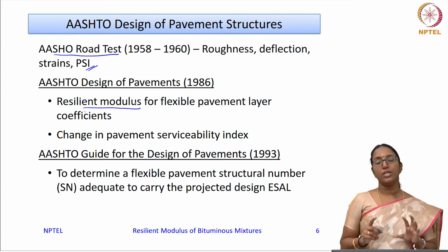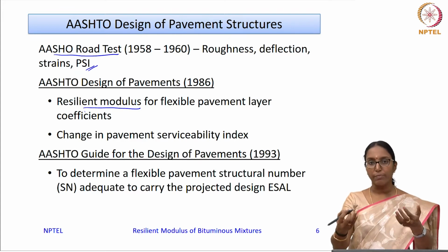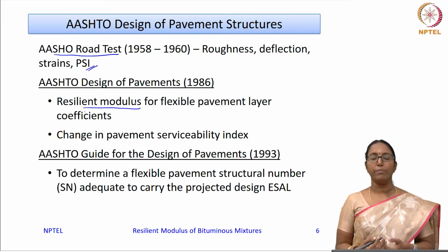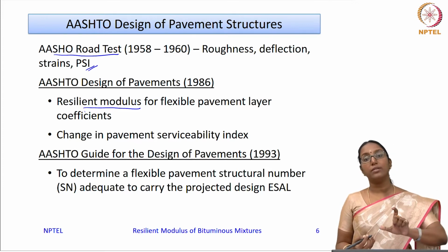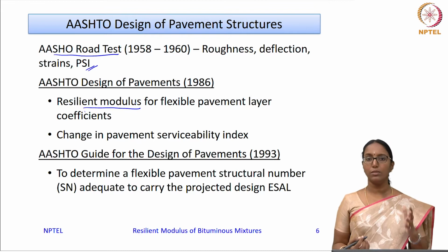Okay, and essentially what you look at is how the serviceability conditions of the pavement deteriorate over a period of time, or what kind of deterioration is permissible, and accordingly you will design the pavement structure. So that was the whole idea.